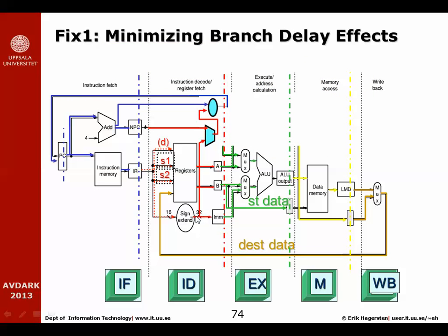All we're going to do is take this immediate and add that to the next PC value. And that, of course, we can do early on. We don't really need to read in the register outcome to do that addition. And then we have to have an extra box not shown here that just tests to see if a register is equal to 0 or not, and then controlling this mux. So that removes some of the problem.